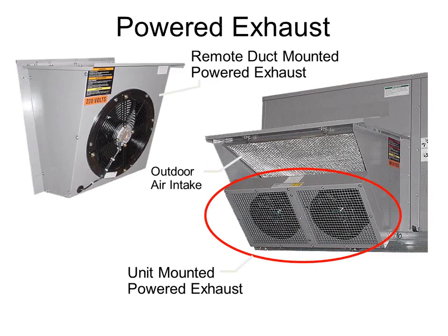That's just showing you an example on this hood over here on the right-hand side. This top pathway here is the outside air coming in, and down here is the exhaust air, in this case 2 fans blowing out. Depending on where you're at, you may have to add a little bit of ducting to this outside air intake because there might be certain rules about distances between the intake portion and the exhaust portion, even though it's not hazardous exhaust, it's general building air, but sometimes they have rules like that in different towns.